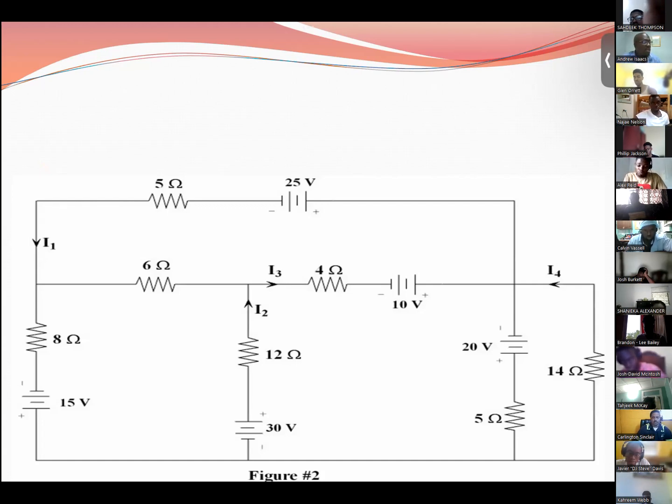There's one other statement there in the printed notes that I'd like to highlight, and it speaks to the maximum power transfer theorem. With all that we have been doing, it really does not matter the magnitude of the resistor that you remove from the circuit, because what you're doing is finding the Thevenin equivalent at that point.